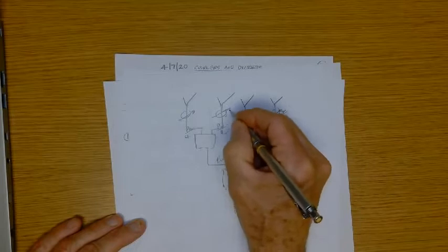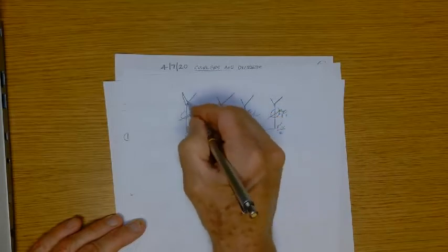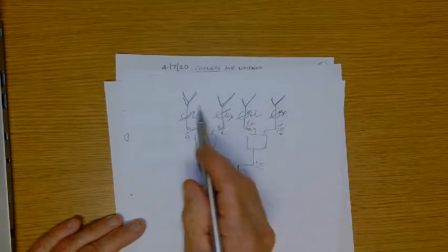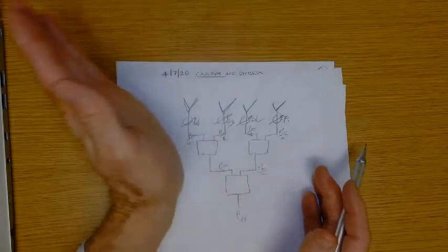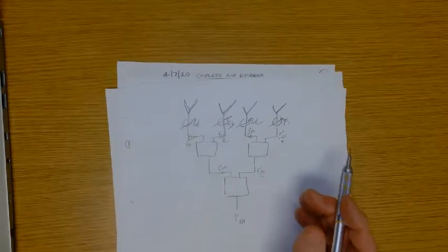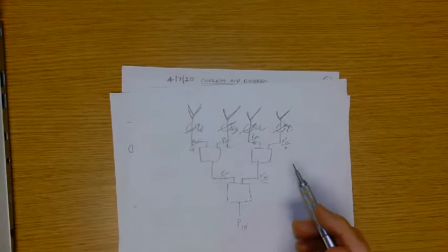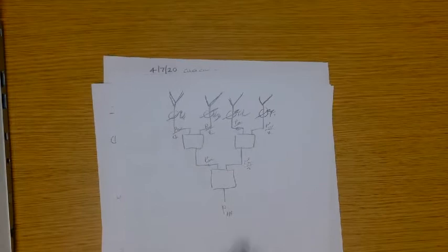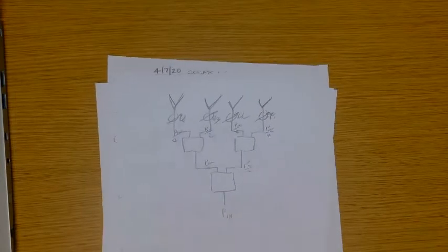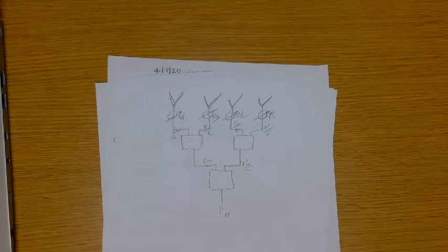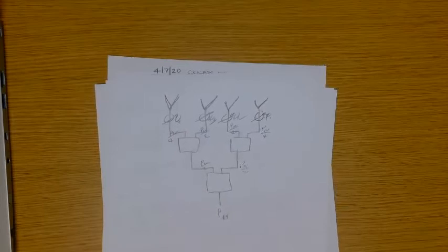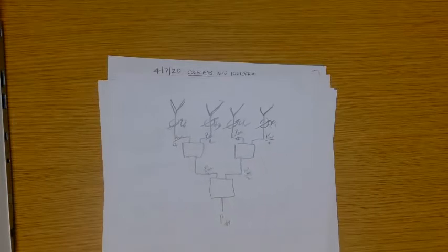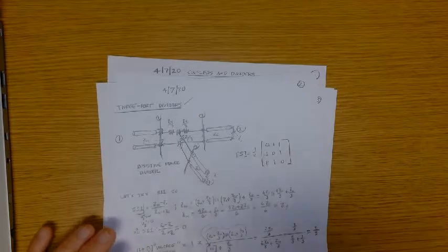Phi1, Phi2, Phi3, Phi4. And so now we can adjust both the amplitude and phase of the signal fed into these antennas so we can steer the beam in space, etc. This is a simplification, but suffice it to say that would be one application of a power divider. We haven't talked about phase shifters, but that's another microwave device that would need to be constructed and could be analyzed via the scattering matrix representation as well. Okay, so application.